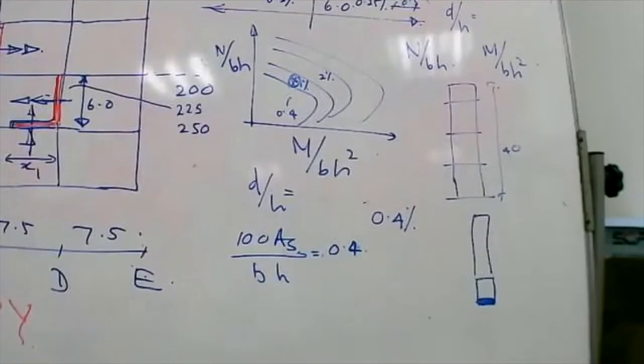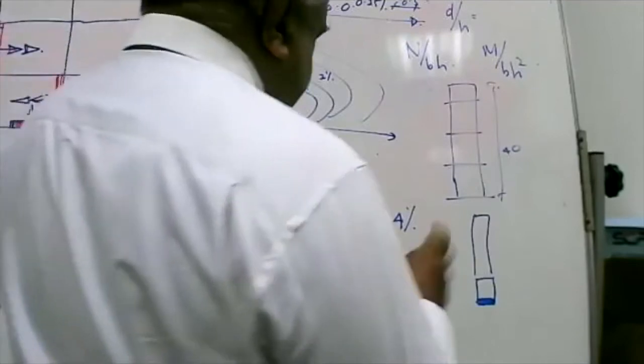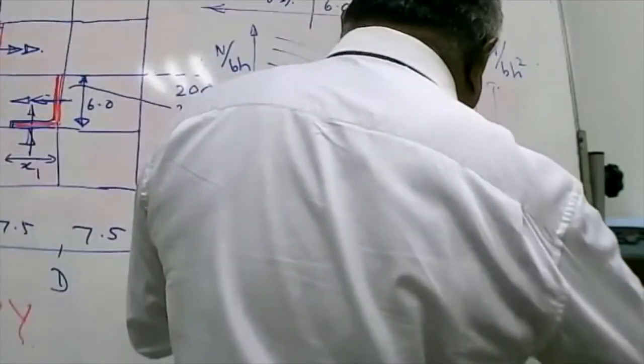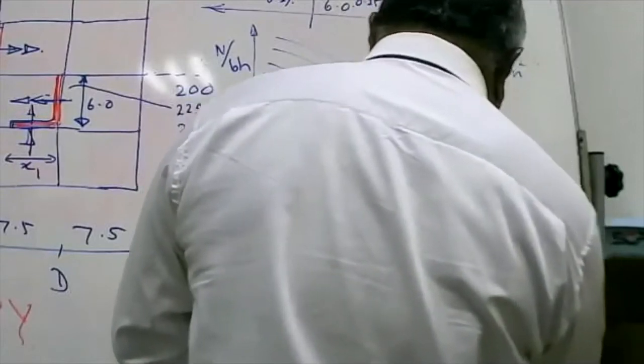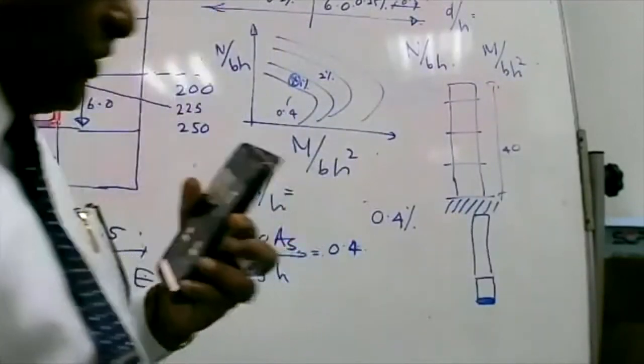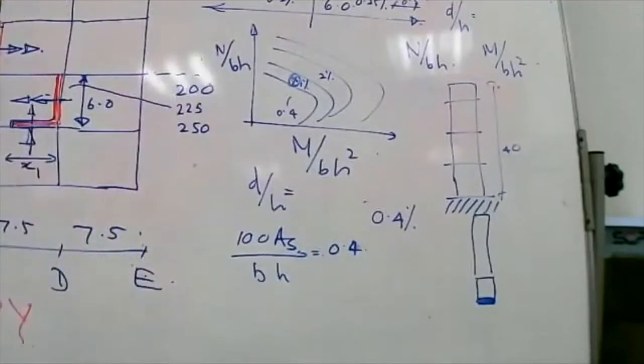One of the assumptions that we take in this model is that the shear walls are connected to the foundation, and the rotation at the floor level is almost zero. And ensuring that with the foundation design will be a bigger responsibility than trying to be very accurate with the superstructure modeling, because the superstructure is not going to do much in this particular structure.